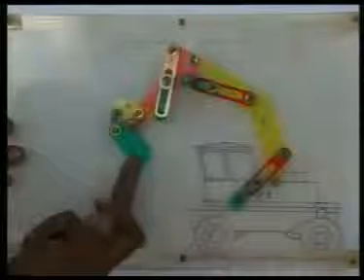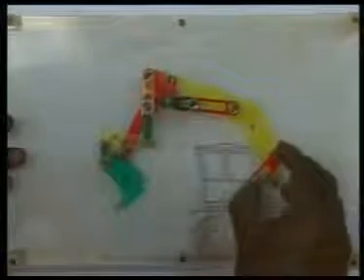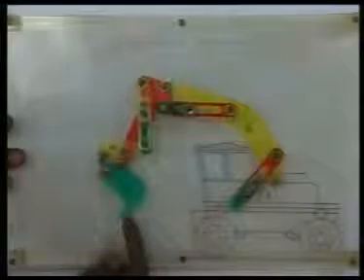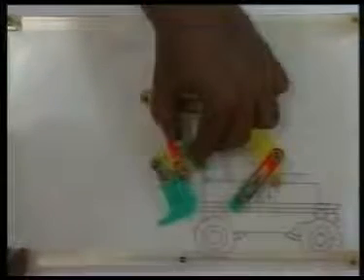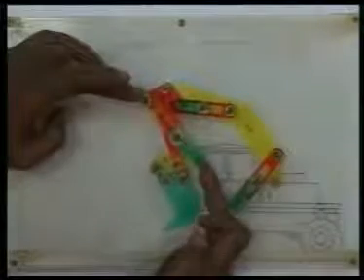the output bin can be moved in this plane of motion. In fact, there are 3 independent inputs, so all the 3 motions, that is 2 translations and the rotation of this output bin, can be independently controlled. We might notice that if this hydraulic cylinder is moved, not much change in the orientation of the bin is taking place. Same is true even for this actuator, whereas the third actuator is mainly changing the orientation of the bin without causing much change in its location.